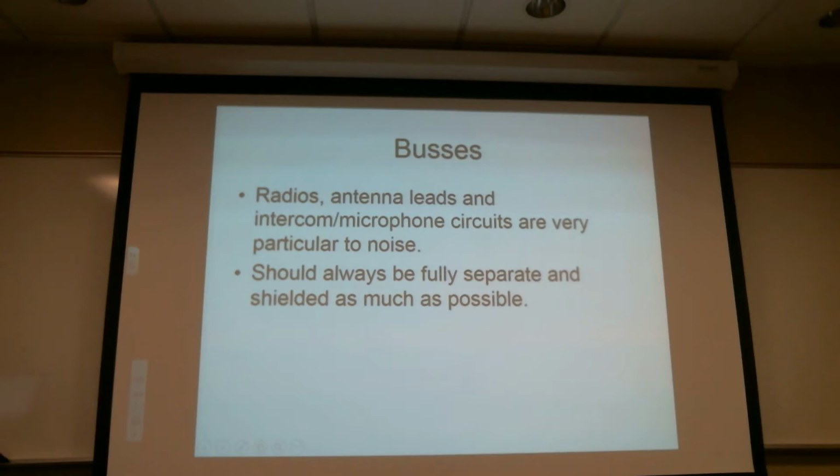If that gets connected to the chassis ground, any noise that's happening on that is going to be like hooking it up to a big white noise antenna. Unfortunately, the amount of amperage on a microphone line, and audio lines a little bit more, is so small that you don't need a lot of EMF to interfere with it.